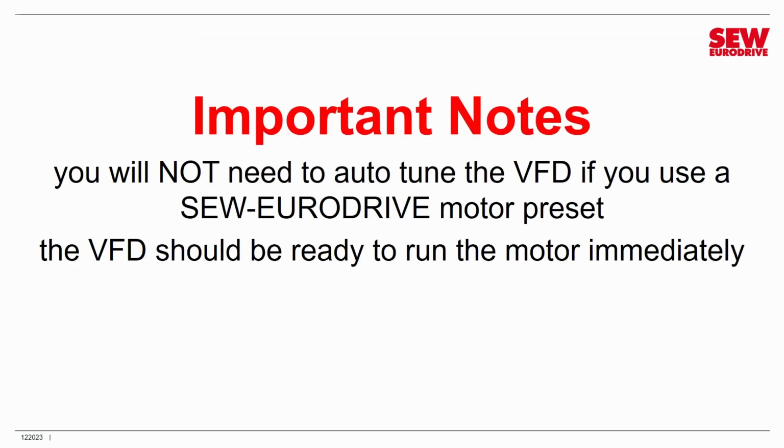Now, this is a big difference. You do not need to run an auto tune if you use the SEW Eurodrive motor preset. You don't need to measure the motor's electrical parameters because the preset has already set those. So even though you factory reset your VFD, it's not going to run an auto tune automatically when you try to run the motor. So this is the difference. The VFD is ready to run the motor immediately.